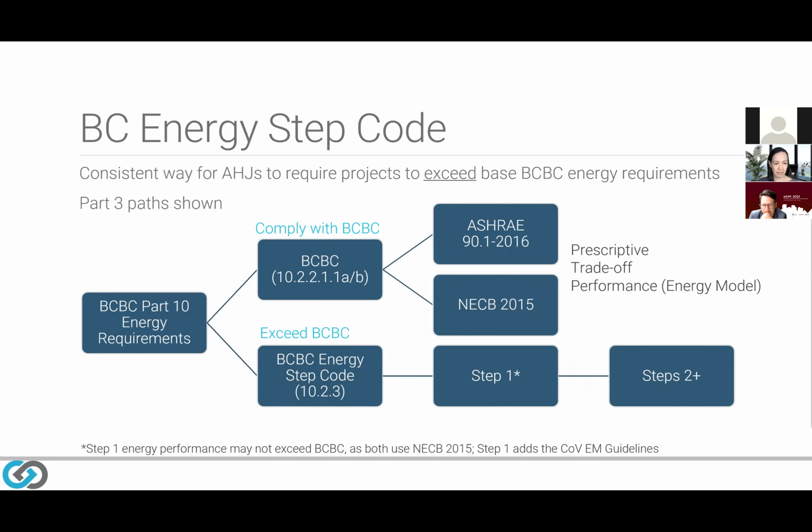Now, the whole intent for the step code from the beginning was that it's a consistent way for authorities having jurisdiction to require projects to exceed base BC energy requirements. So if you can see my pointer here, just as a note, I'm showing right here Part 3 energy compliance. So that's buildings that are basically not single family or duplex. And that's the world that our firm practices in more. I will be talking a little bit about Part 9 in this presentation, but more often I'm talking about Part 3.